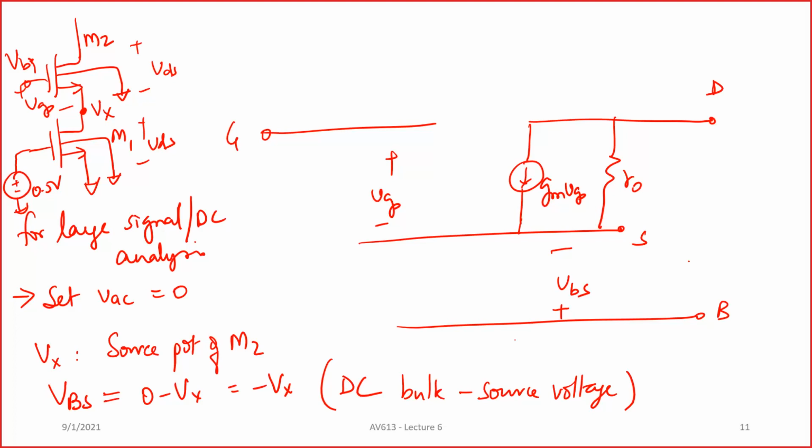Similarly, for a large signal, can we define some sort of slew rate? Actually, I understand what you're trying to say. Let me clarify. Slew rate is a time domain related parameter. When you have a very large signal step, for example, when we look at OTAs, and especially when you put OTAs in feedback and try to drive capacitive loads and so on, the current through your OTA or your op amp will limit this.